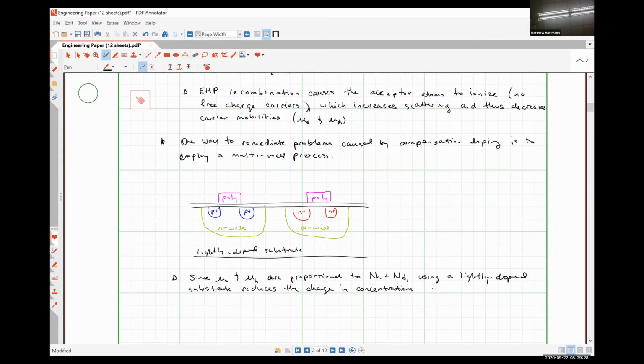But one of the reasons that you are going to want to have the substrate doped to some extent is because, like right now, we're looking at our transistors as 3 terminal devices, right? So we have source and drain, which are going to be our P plus or N plus implants, depending on which transistor we're looking at. And then we have our gates, which are our polysilicon. But there's also a 4th terminal on a transistor that's the body terminal. And to create our body terminal, we need our substrate to be slightly doped. Otherwise, we're not going to actually have a good contact.